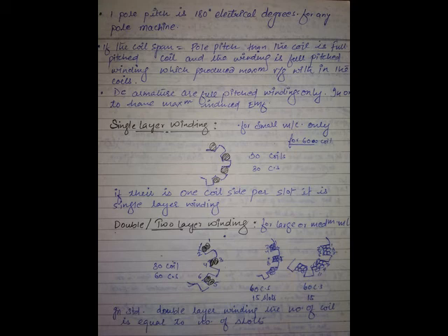This is only one set of winding, with all the 12 conductors making one set. Instead of that, take 6 conductors. You will start with the first conductor, connect all the 6 conductors and come back to the first conductor. All the 6 conductors make one set.